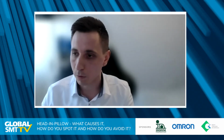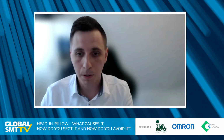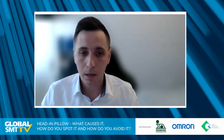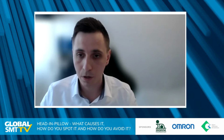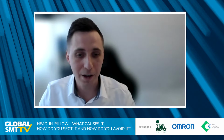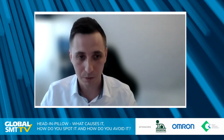Right. Thank you very much, Trevor. Basically, I just already introduced this is a very interesting point if you are talking about how to spot it, how to inspect it. Especially if you are talking about some non-destructive tests, if you want to test it in mass production, 100% sample inspection, at the beginning in your process, for sure, you will recognize very quickly that the AOI is not capable to do it. And you will move directly to the X-ray inspection.